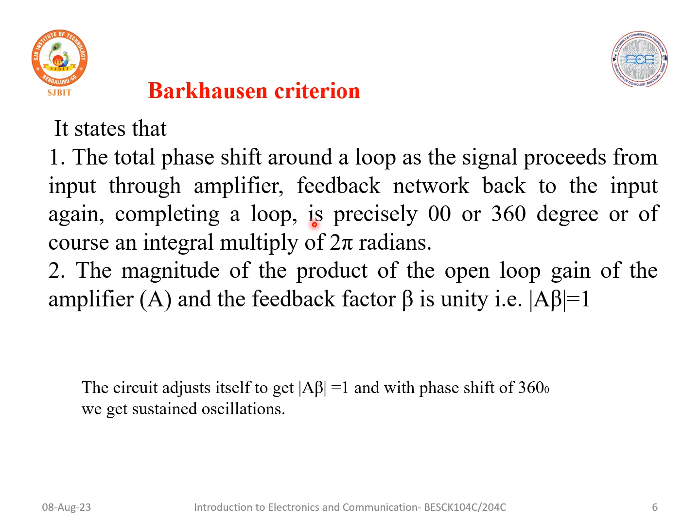So overall, the feedback must be positive, and the phase shift must be 0 degree or 360 degree.